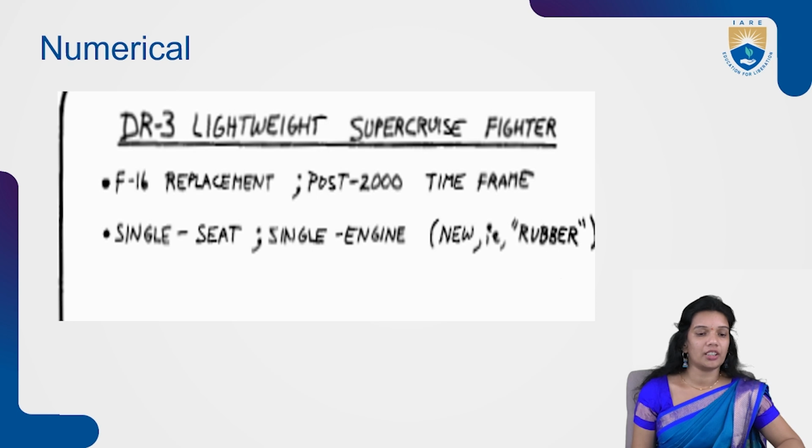And we have seen what all the different things are that need to be added in the rubber engine sizing. All of them are going to be the same. We need to do the weight estimation, or calculate the fractions. All the segments need to be calculated. Then we calculate the weight estimation, empty weight, fuel weight. Then we do some iterations by guessing the weight and coming up to a calculated weight, right? Except that we are going to include here the weight drop. If there is any payload drop or any weight drop, those parameters are also included, and we are refining the complete sizing of the given aircraft.